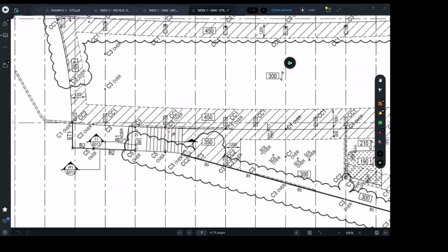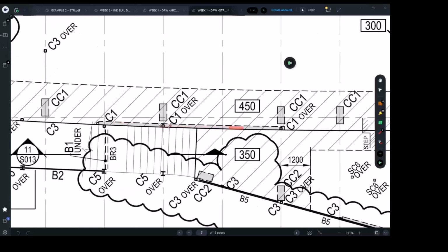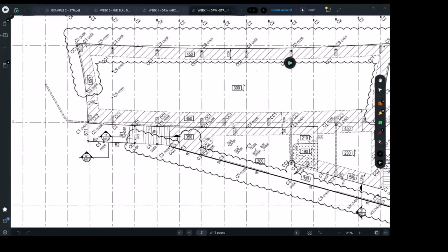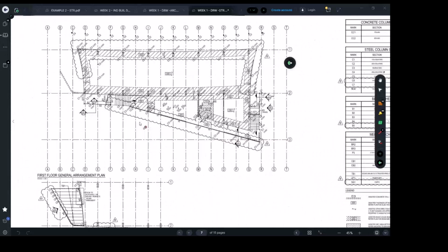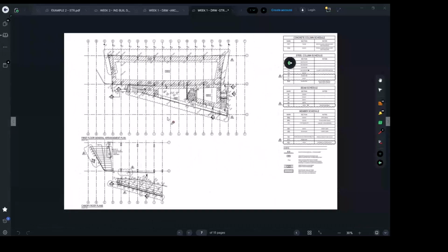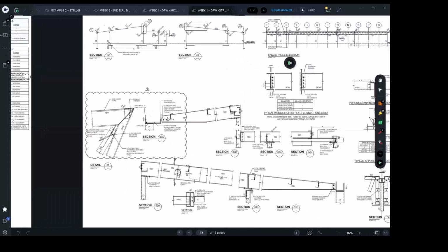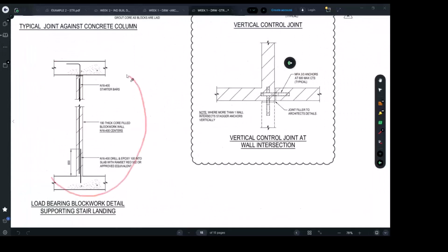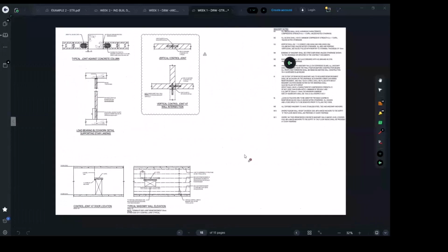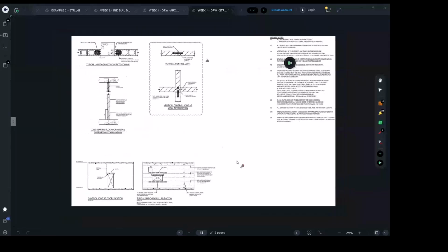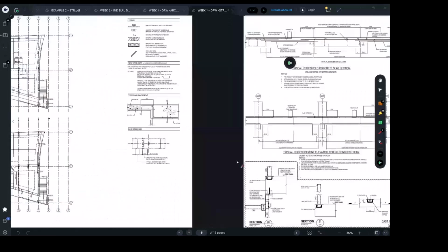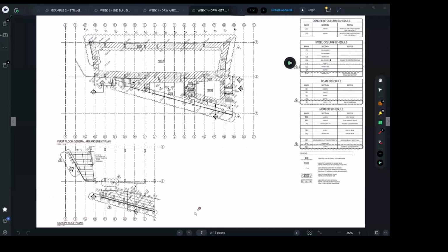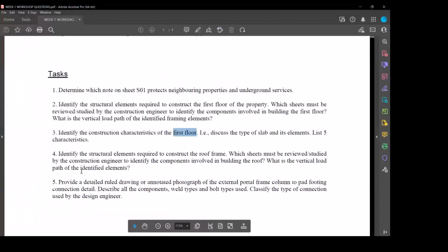You can't just physically connect the block wall after you build the slab, because you have to let the slab sit on it, because you need to use the block wall to stabilize it for lateral load. So see things like this detail here. Okay. So I think I've listed those 5 special features with the slab, and we've answered this question.